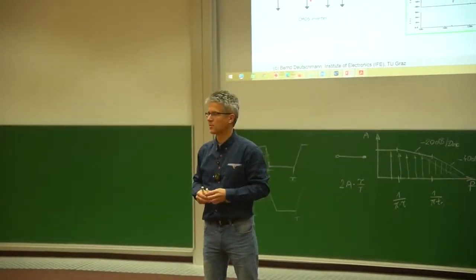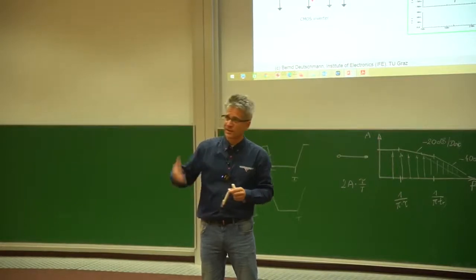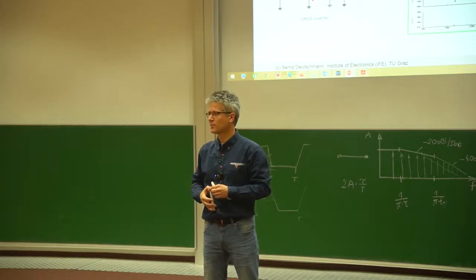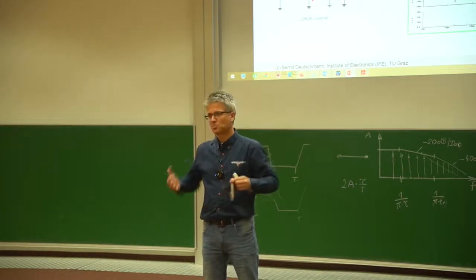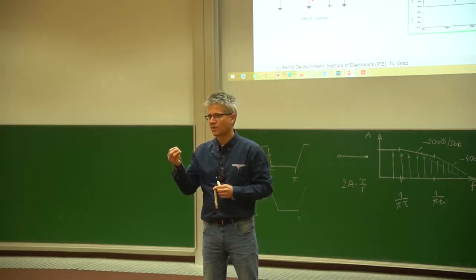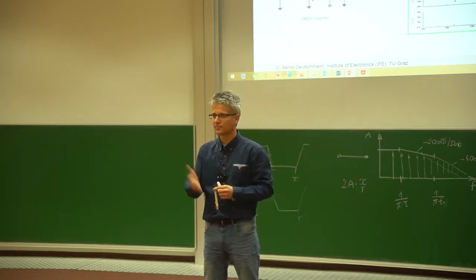Okay, but very often the customer wants to have some freedom, and very often they are placing a 10 nanofarad capacitor for ESD purposes. So this is a quite big capacitor. So I think the best way would be to design something internally that can handle any kind of capacitor.